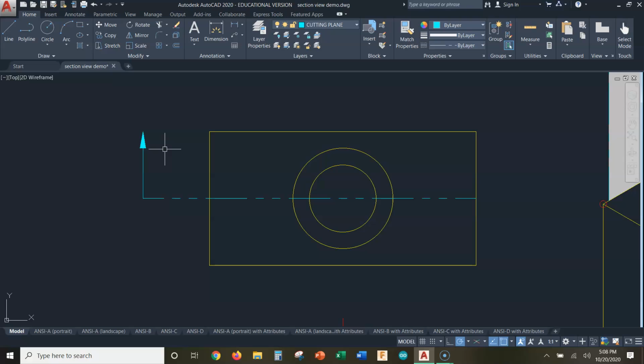Right? Now we're not quite done yet. Again, this is according to the CAD standard, we actually need the arrow to be twice as big as it is here, as it comes in by default. So to do that, we're going to use the scale command. We select just the arrow with the window. I'm done selecting objects, so I'm going to hit the enter key. I'm going to specify my base point right at the tip. I'm going to scale it by a factor of 2. And then there we go.